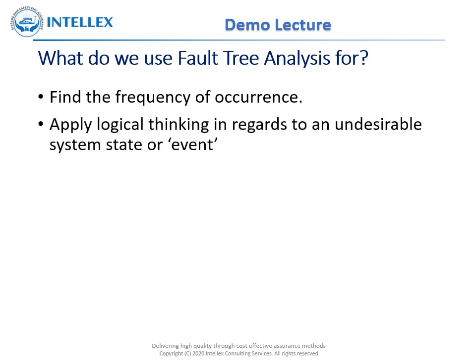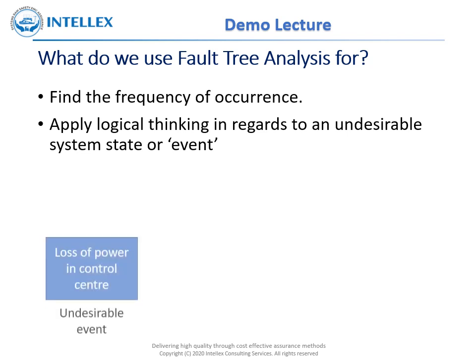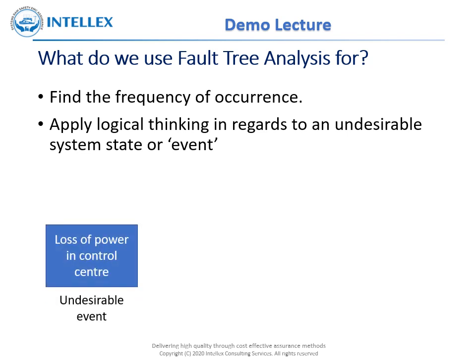Designing fault trees helps us to approach failures in a systematic way. We translate our system knowledge into a logical representation of how a particular event might occur. We start every fault tree by defining an undesirable event, which we call the top event. For example, the loss of power to a railway control center would be highly undesirable.